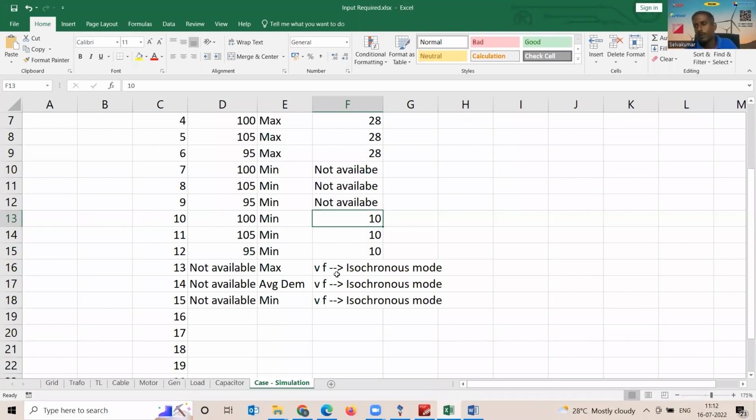And all these probable combinations you need to run before deciding OLTC range, impedance, and probably voltage tolerance, power factor corrections, all these things. By running a load flow for a single case, you cannot conclude something is enough or not enough, which is another important aspect. Before you decide on a power factor correction capacitor, you need to look at all possible combinations. What I mean by that? Shall we conclude that this much capacitor is sufficient by running only one load flow case? The answer is essentially no. Why?